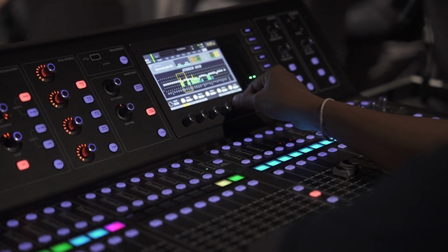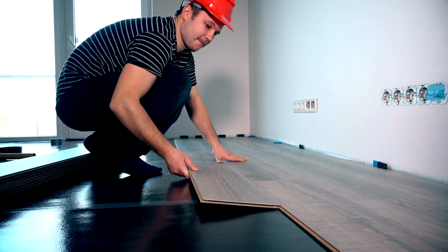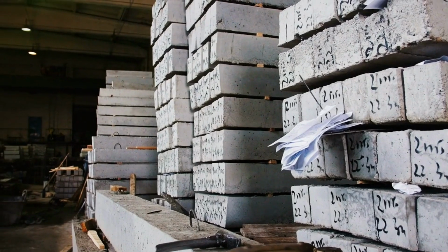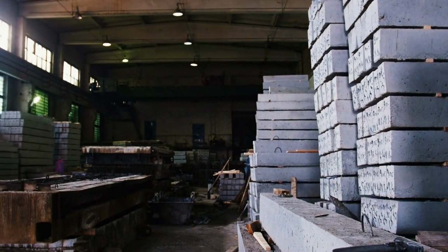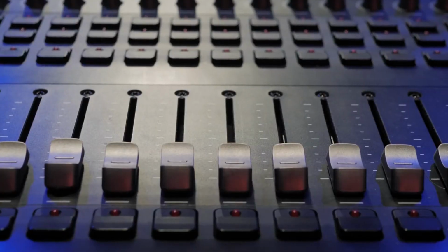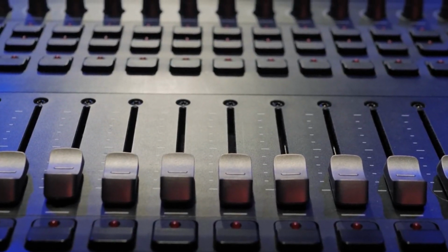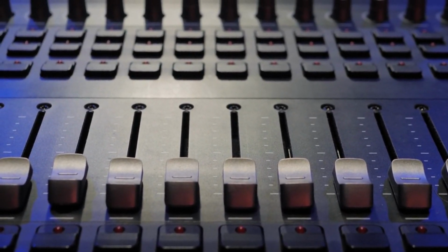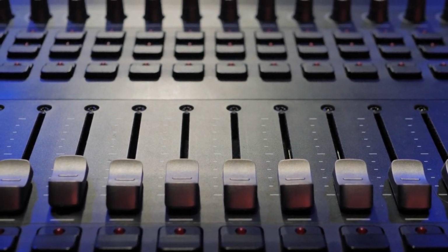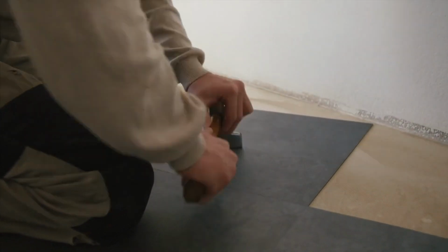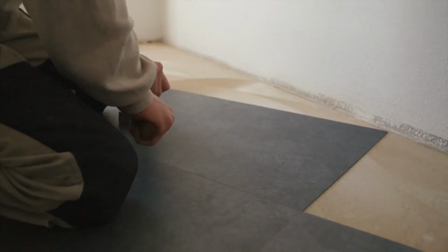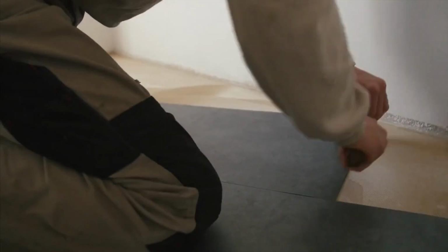Floating floors. Floating floors are used to reduce impact noise and vibrations. This technique involves installing a secondary floor on top of a sound-absorbing layer, such as rubber or foam. The floating floor is not directly attached to the structure of the building, which helps to isolate sound and reduce transmission. Installing a floating floor is a complex process that may require professional assistance, but it can significantly improve the sound isolation of a studio.